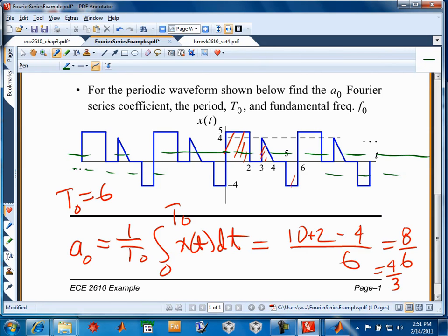So that's where the waveform sits half the time above and half the time below, when we're looking at it relative to 4/3. Later on in electronics, you'll learn that if you send this signal through a DC blocking circuit, which is a capacitor circuit, that's how it will sit when you look at it on the oscilloscope after it comes out of that DC blocker. So there's other aspects of average value that show up in electronics.